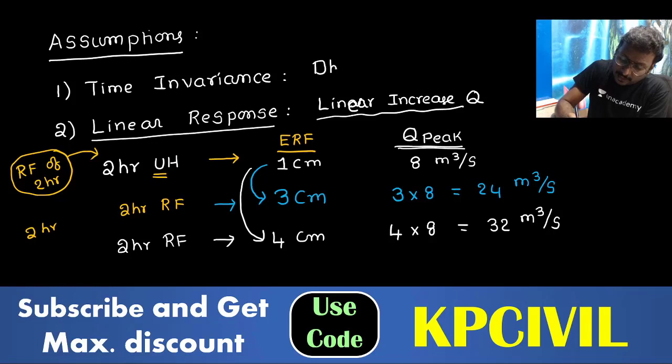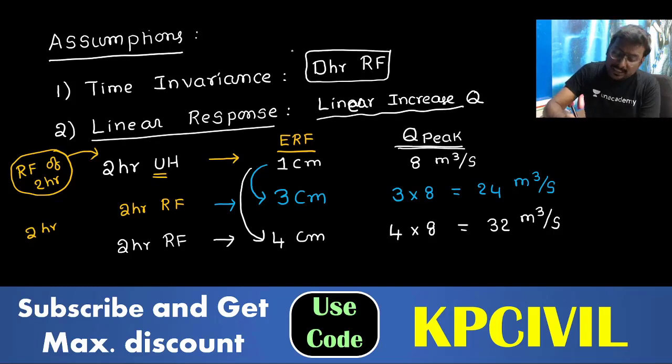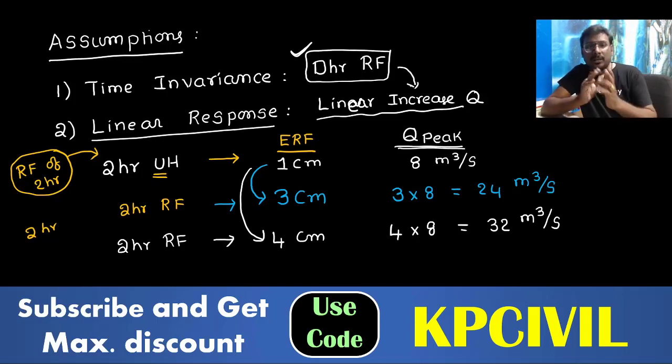D-hour rainfall may occur today, day after tomorrow, after 1 year, after 2 years, after 30 years. For the same D-hour rainfall, you can apply the unit hydrograph, considering a linear increase in discharge. So these are the 2 assumptions made by Sherman for the unit hydrograph: time invariance and linear response. Very important assumptions.